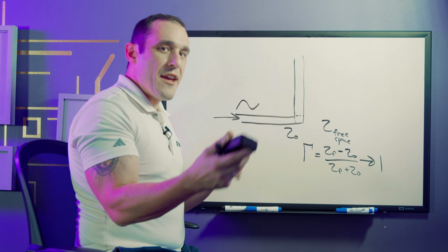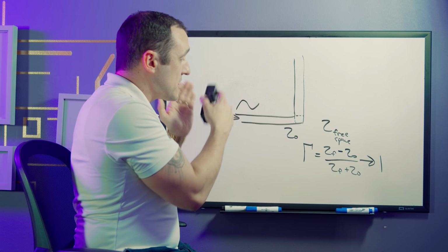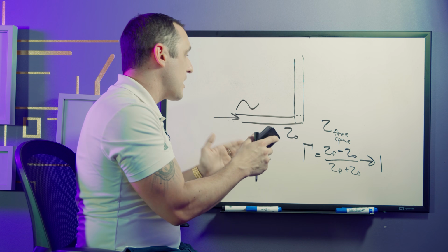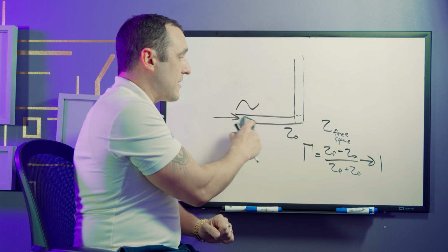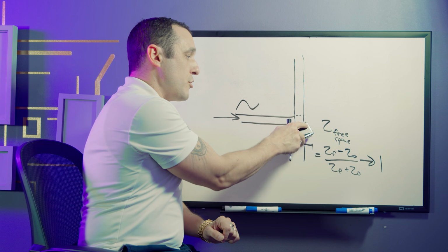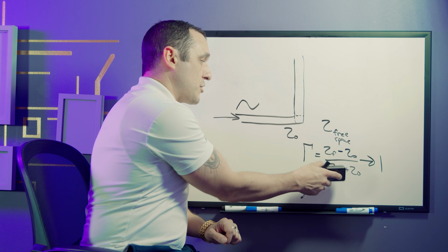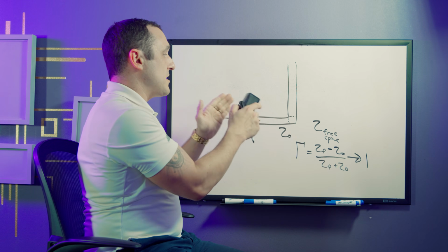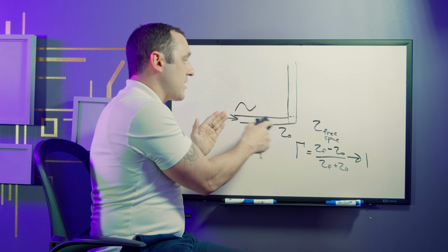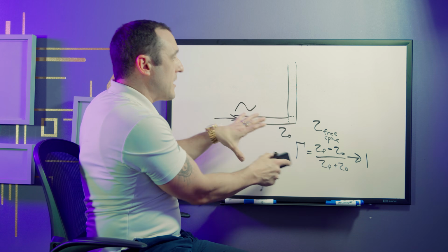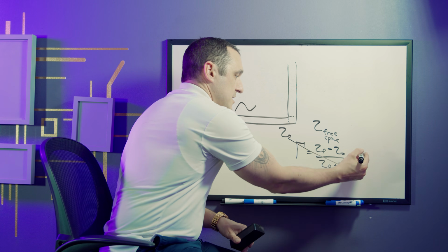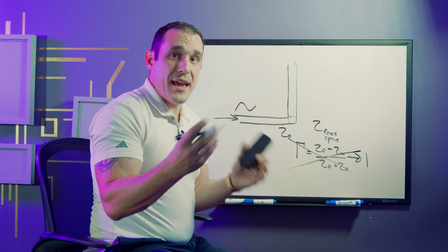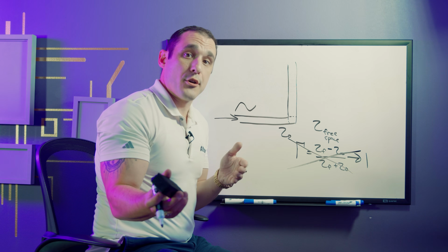Now, we need to get away from that when actually looking at how signals propagate on a PCB, because the reality is that signals on a PCB do not propagate like this and then reach a discontinuity and then experience a big reflection as shown here. They actually exist in the space between the conductor and the ground plane, in the dielectric that makes up your PCB. So this is not a physically accurate picture because it's based on a physically inaccurate description of how current flows.